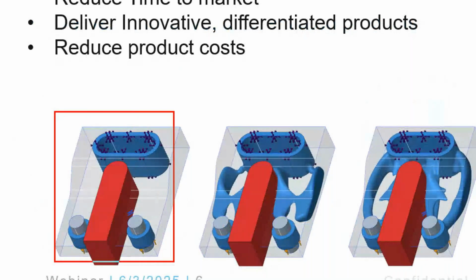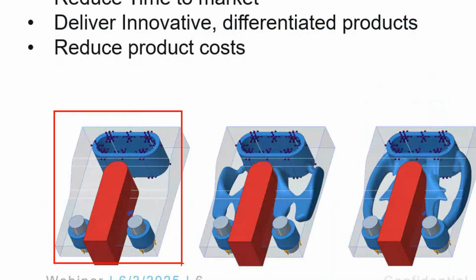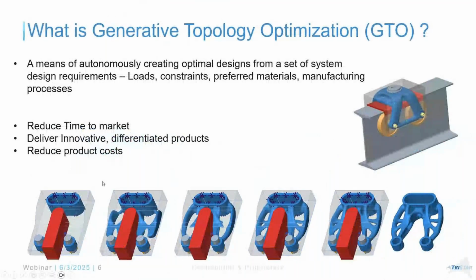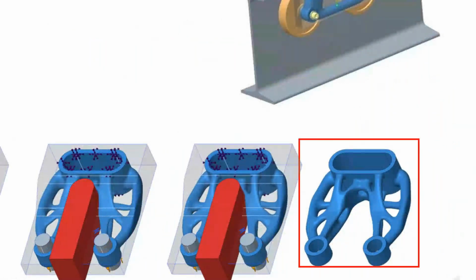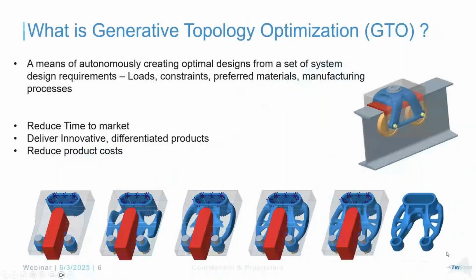The transparent areas of volume, I'm giving a starting geometry. I'm kind of blocking it with my red excluded body here. I have the blue bodies where I want you to preserve those, so I don't want you to be changing those areas. And then you see how, with my constraints, it's able to build that geometry for me, what you see on the top right side, depending on the constraints that I've given, right?